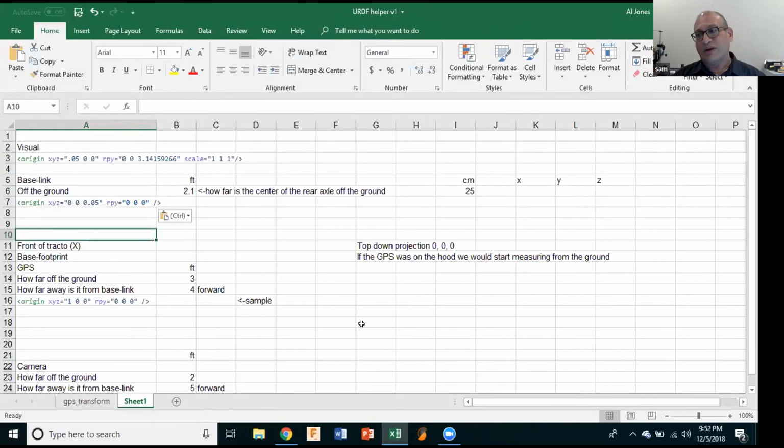Now you're defining the joint, and what's the GPS joint? Let's say, for example. So where is that GPS joint? When you define the joint, you're just going to say my parent frame or parent link is my base link. My child link is my GPS link. And how it is connected, so where you define your X is 1 from parent, your Y is 0, and your Z is your height of where the GPS is mounted.